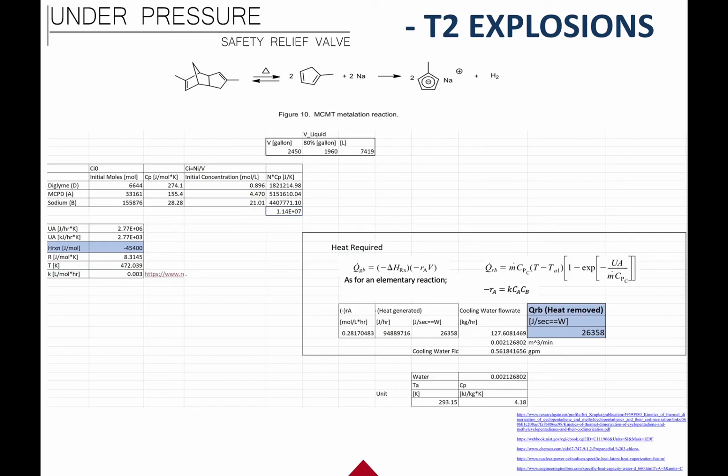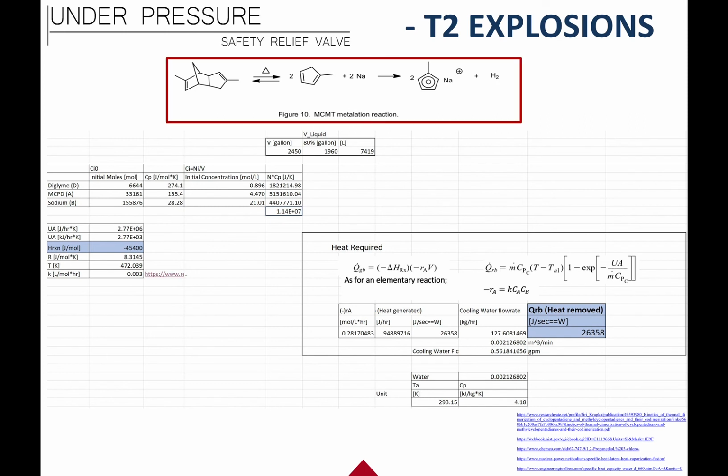When considering the explosion that occurred at T2 Lab, we primarily focused on the first exothermic reaction that occurred, because if the cooling system had succeeded, the second exothermic reaction would not have happened. To determine proper design of the cooling system, the amount of energy it was giving off, at minimum, had to equal the amount of energy being generated by the batch reactor.